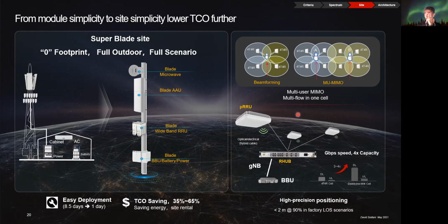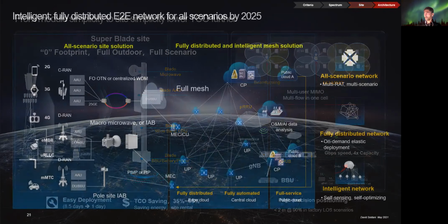Indoor deployment follows pretty much the same type of configurations. We have a very simple system. So you have Pico RRUs, which are the radiating elements with the possibility also of beamforming, and that would allow us to achieve speeds, as you see on this graph, of even a gigabit per second. And the distributed massive MIMO configuration, the one you see here, using beamforming, can improve the capacity, so that means the number of accommodated end users at a given end user quality, by a factor of 4.